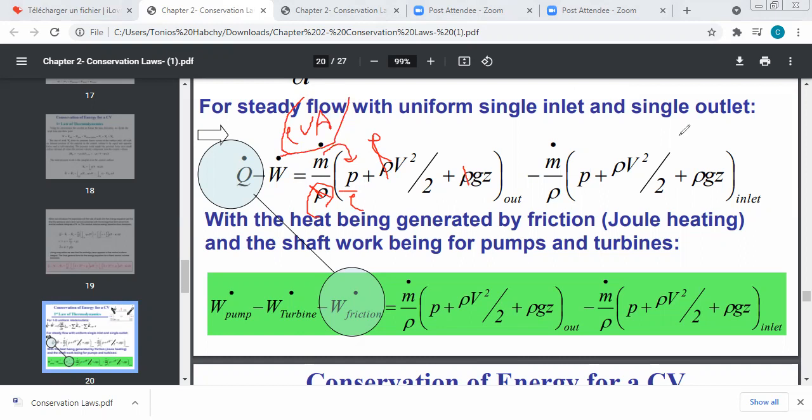And then for the inlet, you will have a similar term, but with a minus because V dot N for the inlet is minus V. We have already seen together that if we have an inlet, and V is crossing the cross section in a perpendicular way, and this is N, V dot N will give us a negative result.